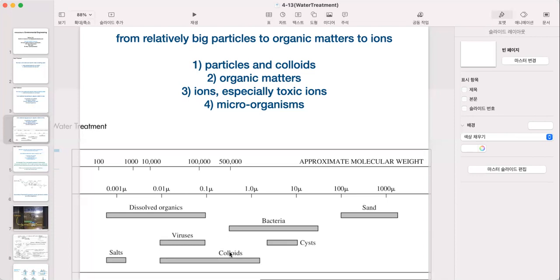And this coagulant chemical bridges, connects a colloid and another colloid to make a floc, which has a much higher size and finally can be influenced by gravitation higher than buoyancy force, and be removed through settlement. And then we can remove this colloid. That's the coagulation process.